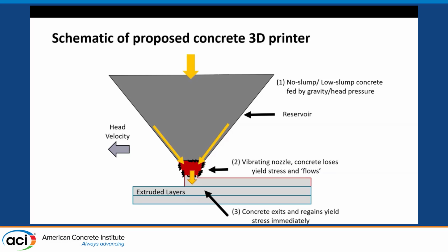But you could have a pressure head. I did not have a 3D printer which could easily do it, so I ended up vibrating to get it there and manually filling the hopper as concrete got consumed. But if you're scaling this up, that shouldn't be a harder thing, right? You could pump concrete there, wait some time for it to lose its slump, or use chemical admixtures to get it to become stiffer.